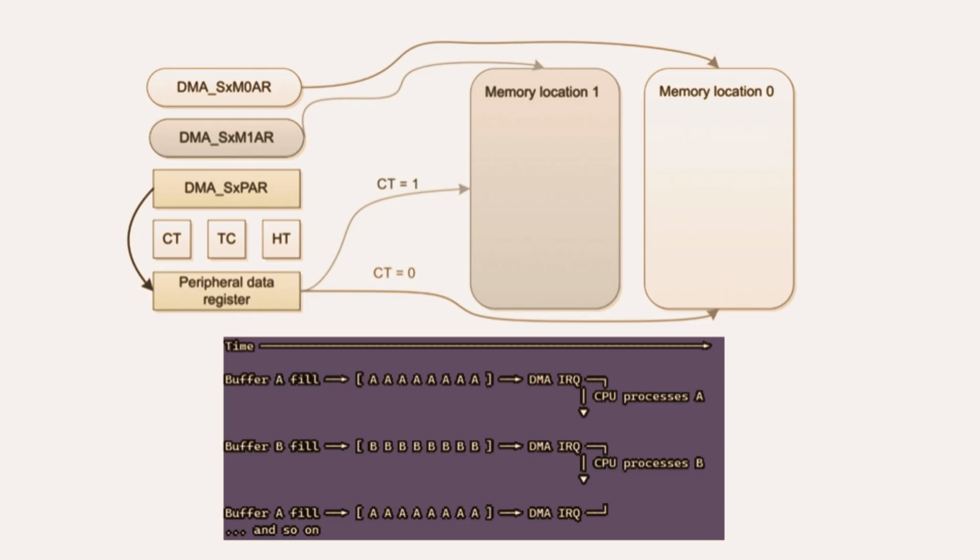complete buffer. What are the benefits of doing it this way? The main benefits are no dead time. DMA never has to pause waiting for the CPU, ensuring continuous data acquisition without gaps. Predictable latency. The CPU gets access to fixed-size chunks of data at regular intervals when a buffer fills. Simplified streaming. It makes it much easier to implement real-time processing pipelines where data is constantly flowing in and being